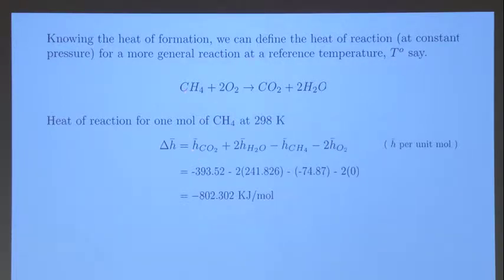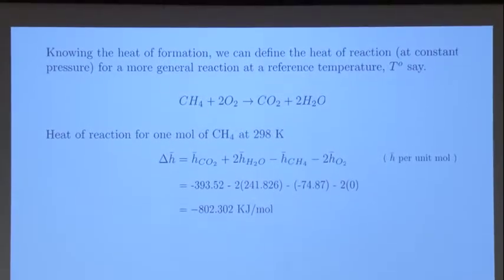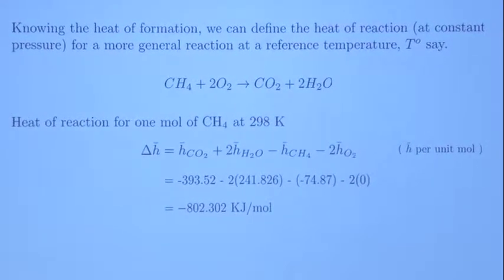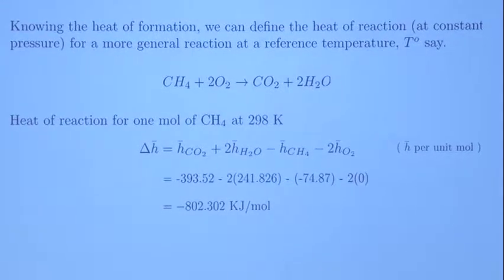So we have 1 mole of CO2 that is formed, 2 moles of water which are formed, minus 1 mole of CH4 consumed and 2 O2. Now O2 is 0, so it's gone. And you look at the tables for the heat of formation of CO2, water, and CH4, and you add them up, and that gives you the heat of reaction of that reaction, okay, at the temperature T naught.